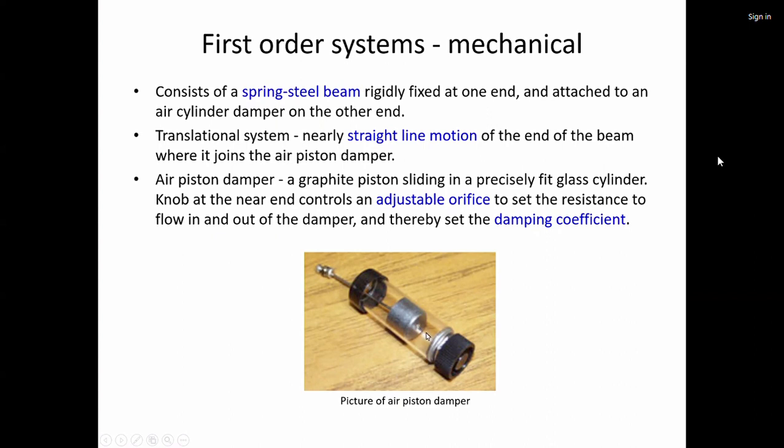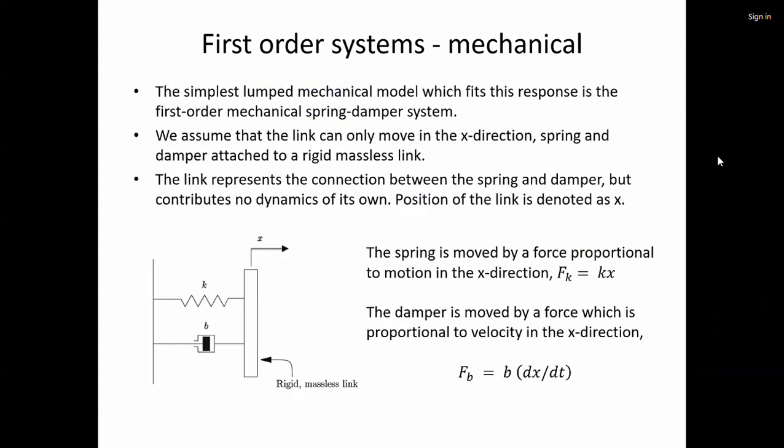So the system damping is because there is some resistance when the piston tries to move down. And because of this spring beam, you have some kind of spring constant in the system. So you have spring constant and you have damping coming into this system. So a simplest representation of this kind of system is called a spring dashpot system.